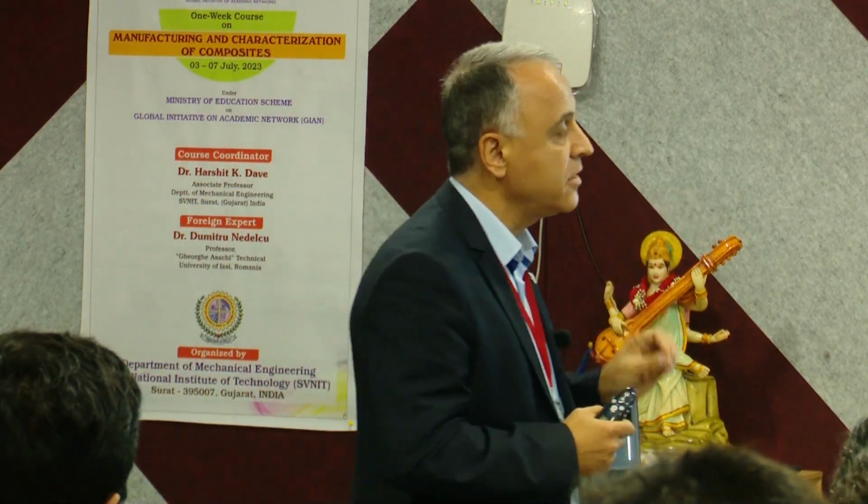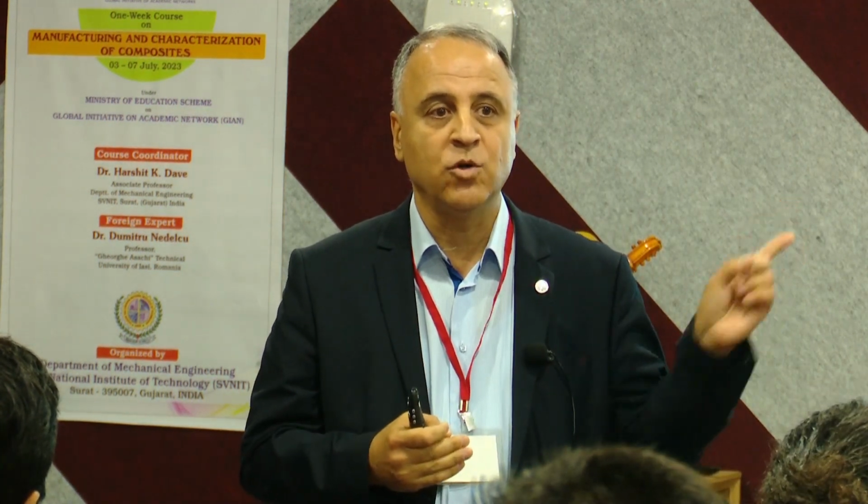Arboblend also processes with conventional machinery and equipment, with high rigidity, high surface hardness, low thermal expansion, and good water resistance. One of our research directions, which I will present tomorrow, is coating the granules of Arboblend with silver nanoparticles using the PVD process. It was a PhD thesis in co-tutelage with the University of Tor Vergata of Rome, Italy, and we did common research and afterwards got the sample with a uniform distribution of the silver particles inside the sample, because the coating process was focused on the granules, not on the sample after the injection molding, okay?